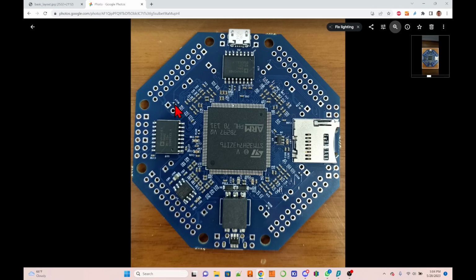One is right over here, and what it does is these 2 pins here, when you interconnect multiple boards, these 2 positions and many other positions, with a pin they go directly to the same pins of the other boards. But if you're not using the system in multiples, but just a single system, then 4 of those positions, these 2 pins need to be connected together. They need to be connected with a 0 ohm resistor. And that little resistor is here. It's called a 0 ohm, so it has no resistance. It's basically a wire. And that connects these 2 pads directly.